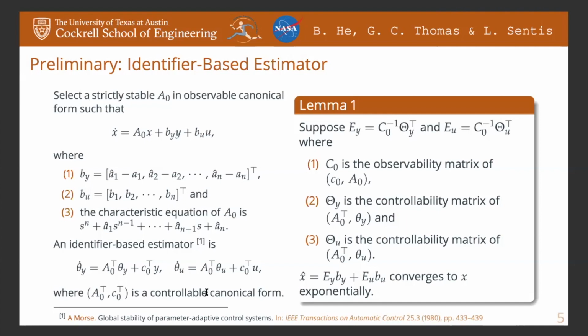We can also prove that the estimated state of this Luenberger observer is dependent on the state of the sensitivity filters and the uncertain parameters. To be more precise, it is linear in the uncertain parameter matrices By and Bu.